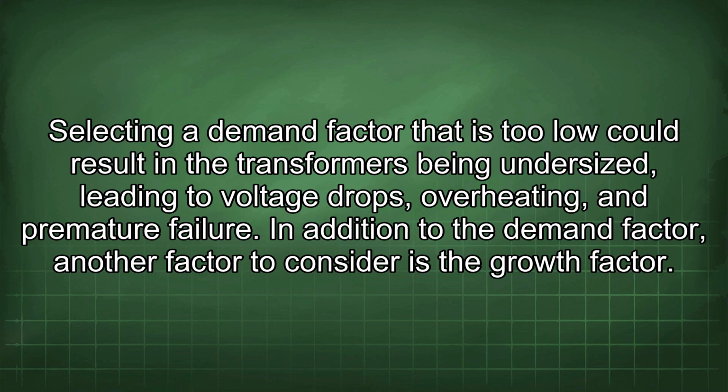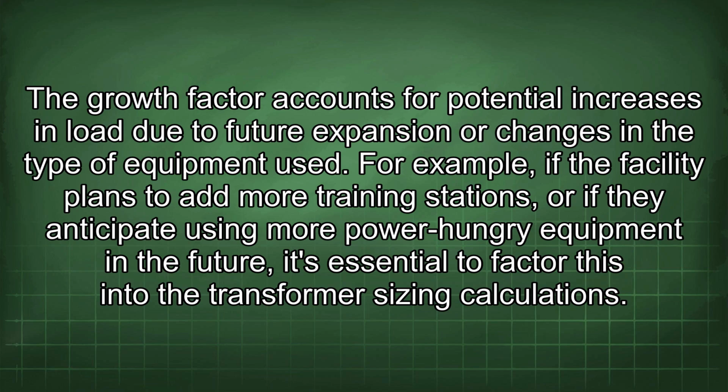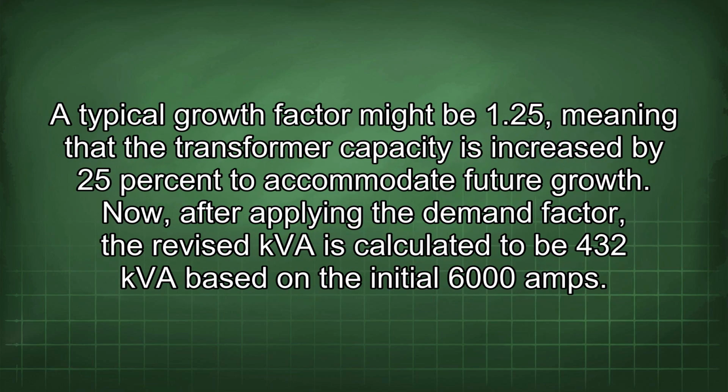and premature failure. In addition to the demand factor, another factor to consider is the growth factor. The growth factor accounts for potential increases in load due to future expansion or changes in the type of equipment used. For example, if the facility plans to add more training stations or if they anticipate using more power-hungry equipment in the future, it's essential to factor this into the transformer sizing calculations. A typical growth factor might be 1.25, meaning that the transformer capacity is increased by 25% to accommodate future growth.